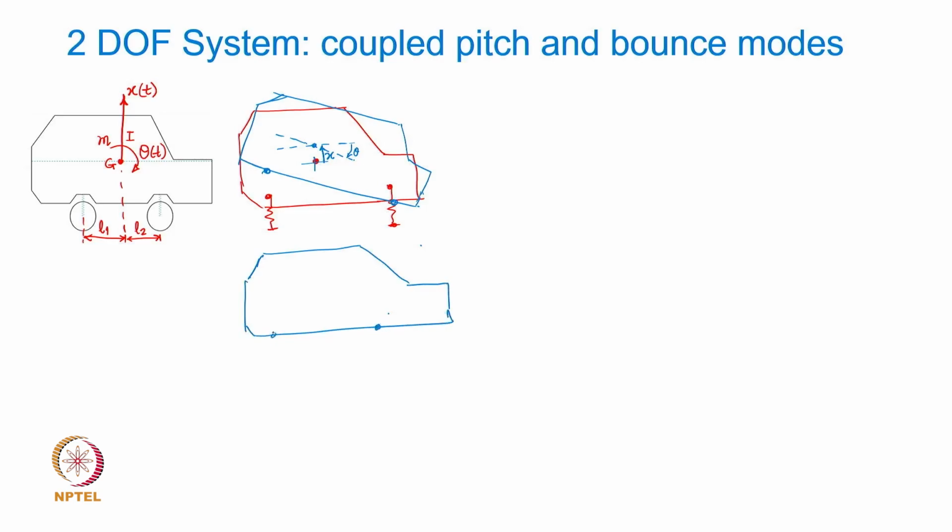All right, so there is a spring force here, and we have to figure out what forces are acting on these spring connection points, because that is the connection of the free body to the surroundings. Now, if the displacement and tilt or pitch motion, x and theta, happens, then it will be shifted like this, with x as well as theta together.